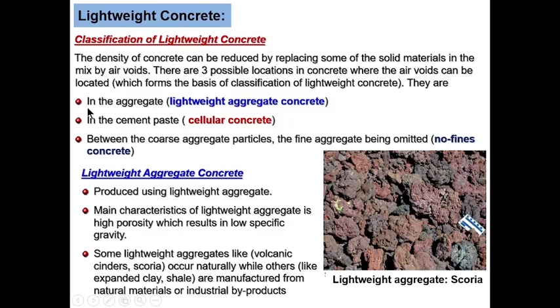So one, it can be within the aggregate. We call that lightweight aggregate concrete. It can be within the cement paste. We call such cellular concrete. And it could be between the coarse aggregate particles, and we call that no-fines concrete.